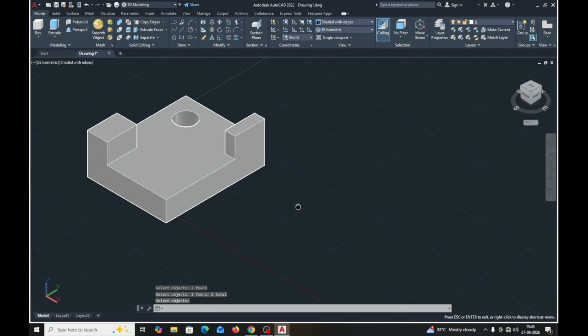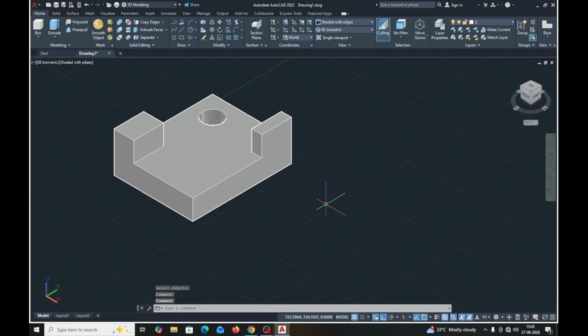One more thing. Now, suppose a 3D model has 6 faces: 1, 2, back, this one, 6 faces. You are seeing here right, front, and top. Okay, 6 faces here. So suppose you want to work on this face, and make a 2D shape here, or on a face parallel to this face. So you will have to change the plane to vertical and the z-axis horizontal. For this you will have to change the UCS from here, right-hand UCS.